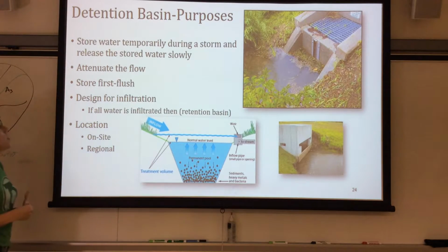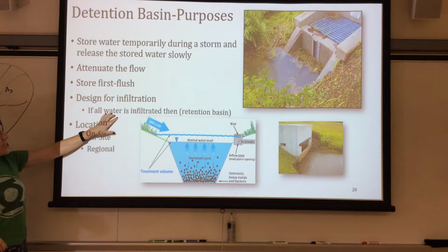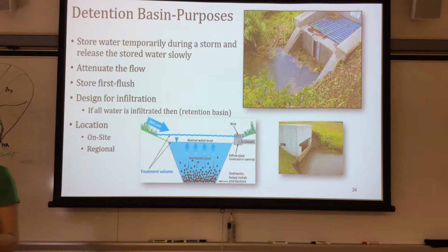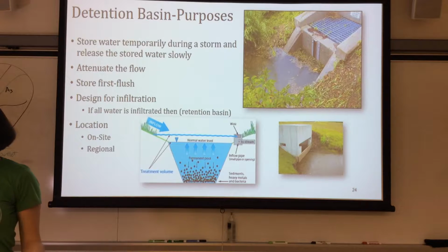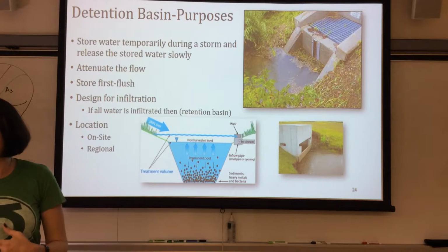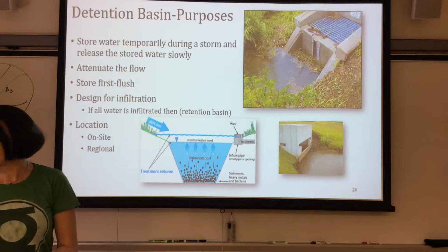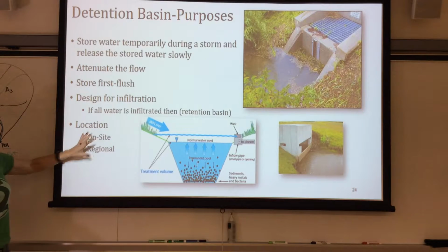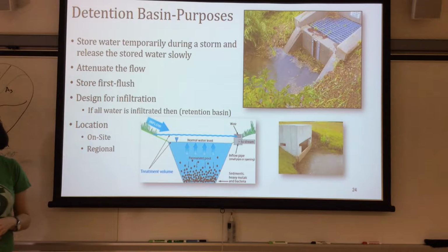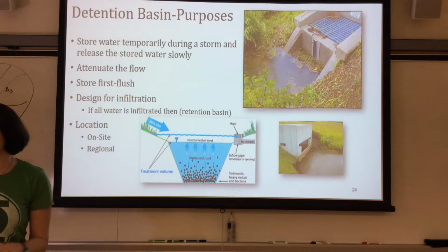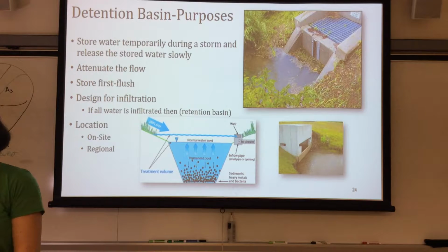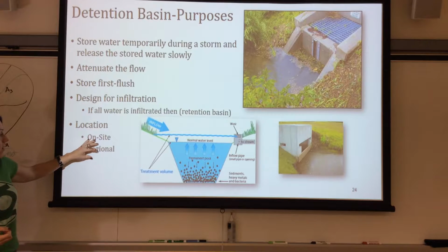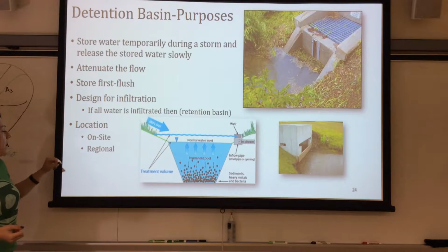Okay? So when you're doing retention, you're designing for infiltration. So in Claremont, you don't see a lot of wet ponds. You see grass in the bottom of the ponds. There's also, depending on the type of facilities that you're creating, another word. When somebody says it's a stormwater treatment facility, they're basically saying it's a pond, typically, or some type of structure or method of holding water.